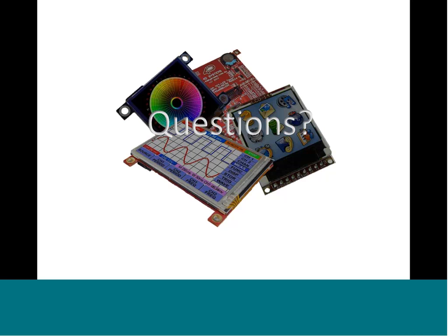Another question is, do you have any experience in using such displays in devices used in vehicles? This is a harsh environment. For example, one of them is temperature. I will refer to the data sheet of the specific module, module specific and platform specific, for what temperature range is supported.